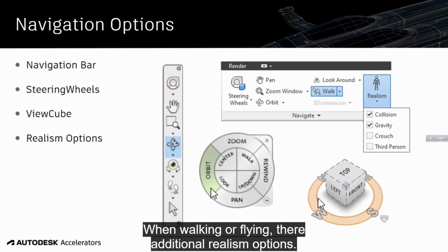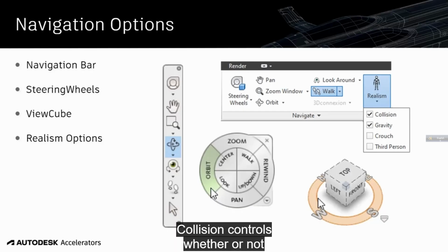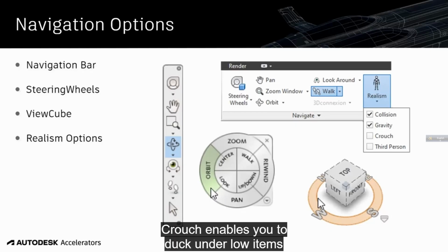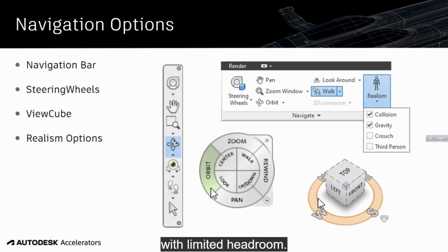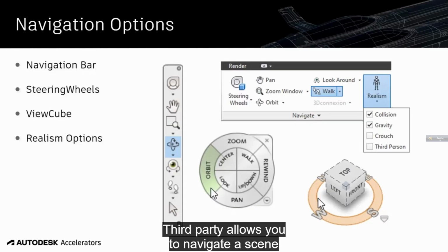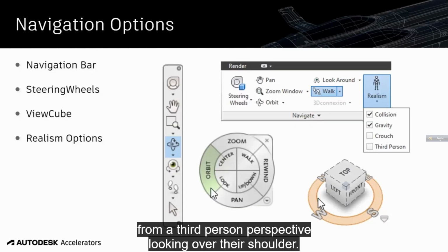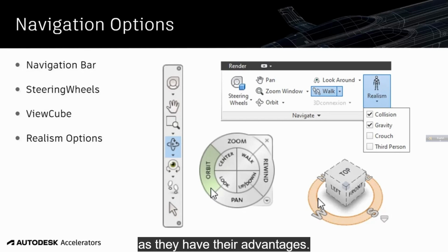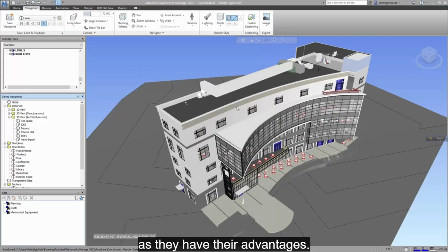When walking and flying, there are additional realism options. Collision controls whether or not you can pass through objects such as walls. Gravity gives you weight and pulls you down onto the surfaces and is used in conjunction with the collision option. Crouch enables you to duck under low items with limited headroom. Third party allows you to navigate a scene from a third-person perspective, looking over their shoulder. Familiarize yourself with all 3 options as they have their advantages.